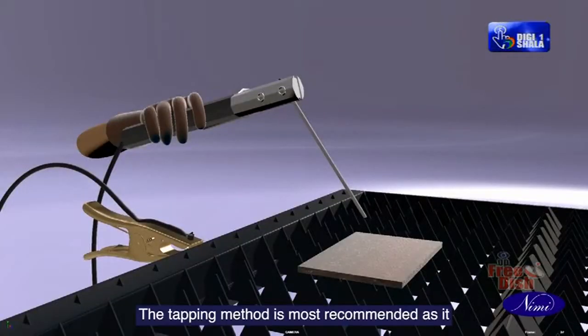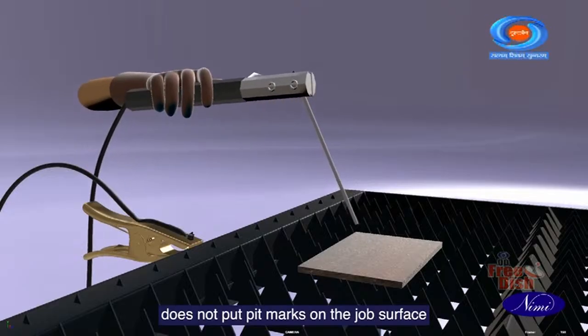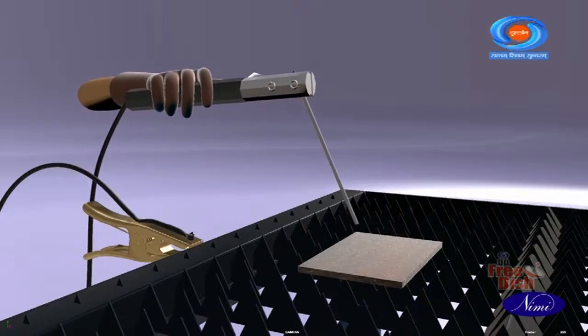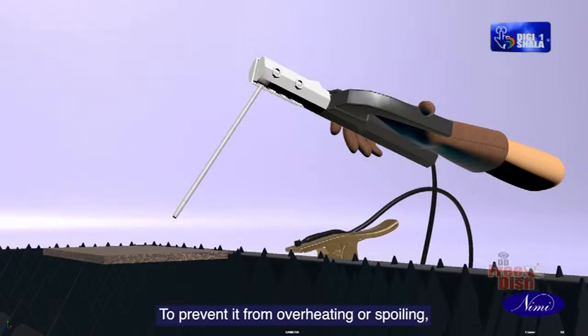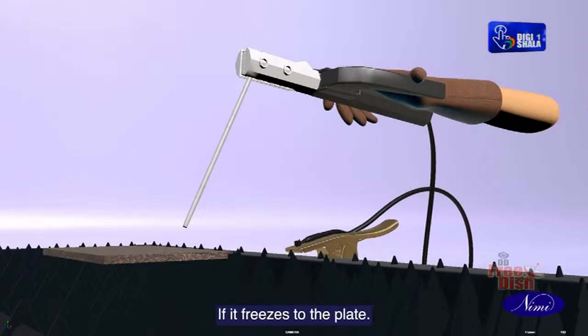The tapping method is most recommended as it does not put pit marks on the job surface. To prevent it from overheating or spoiling, the electrode should be quickly released by twisting the wrist if it freezes to the plate.